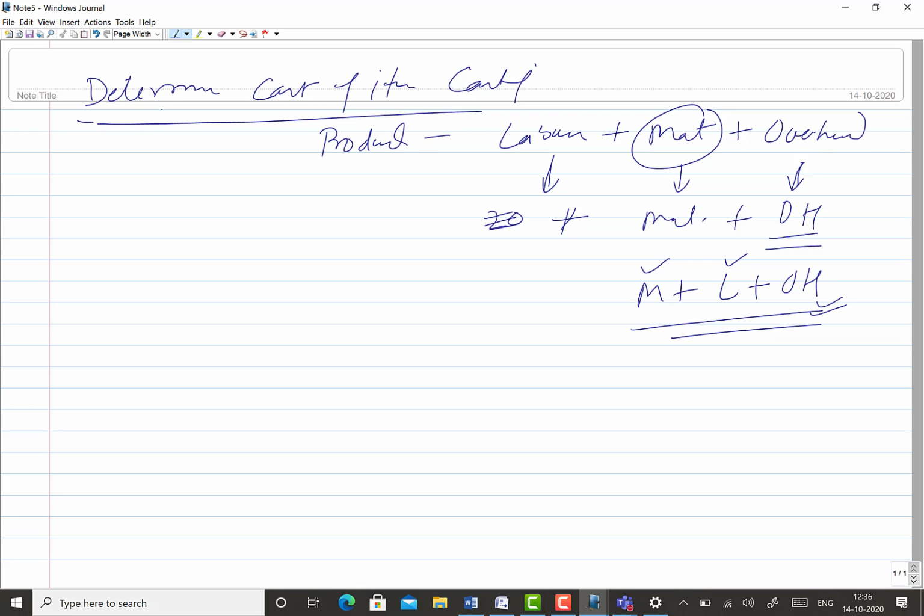Standard time can be used in costing basically: to determine the labor cost plus overhead cost of production of one item, plus you can add the material cost. This will come from a different source, but certainly the overhead and labor cost related things can be identified from the standard time.